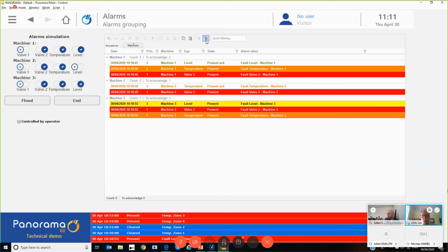Hopefully I included this when I was talking about it. But when you switch modes, particularly from a current alarm mode to a history mode, you've just taken away the operator's ability to see his current alarms flowing. So you need some other indication on the screen, and that could be as simple as a big button that flashes when there's a new alarm.